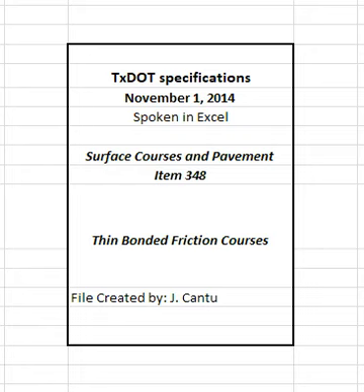The coarse RAP stockpile will contain only material retained by processing over a 3/8 inch screen unless otherwise approved. Fine RAP is not allowed in PFC mixtures. The engineer may allow the contractor to use an alternate to the 3/8 inch screen to fractionate the RAP.